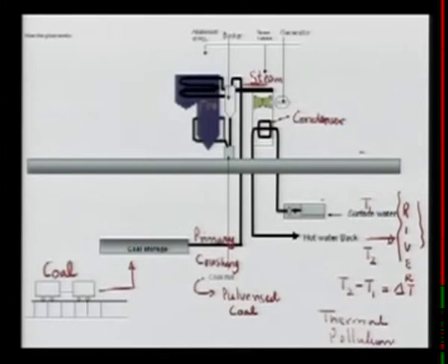But let's see what further happens in the power plant. As you can see here, you also need at times makeup water, because all the steam at some point will not be enough. So you see here the word industrial water. Industrial water needs some cleaning, okay, especially to demineralize it, take out the hardness and bring it up here and do the makeup water. So industrial water is the makeup water, as you can see here.